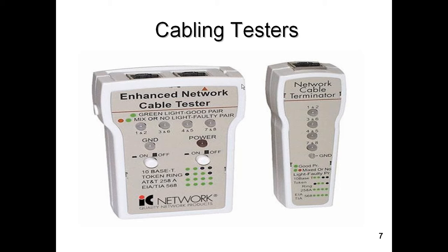And along with your tester, you need jumper cables to connect this tester into the jack on the wall or to connect the other end into the patch panel. Make sure your jumper cables are good ones, and make sure you've got spares. What can often happen with jumper cables that are constantly used is a little spring clip on the RJ45 plug will lose its springing capability, making it loosen the socket so it keeps sliding back out. That's bad. Always have good jumper cables with you, and always have spare ones. They're inexpensive. Always have spare jumper cables.